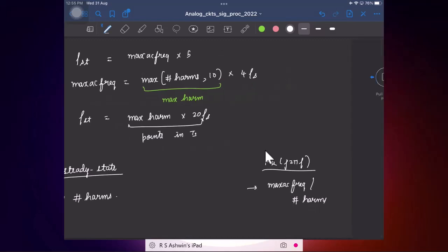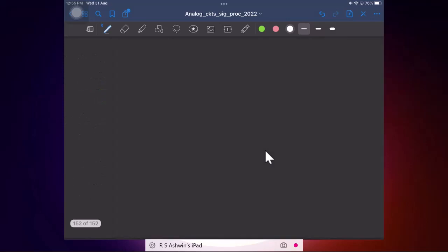And so let us say we have an LPTV system and you are interested to find the frequency translation to or from 100 Fs. Now you can do two things, right? One, I can set the number of harmonics to 0 because I am not interested in the steady state spectrum. So I don't want to waste resources in computing the spectrum. I'll set it to 0.